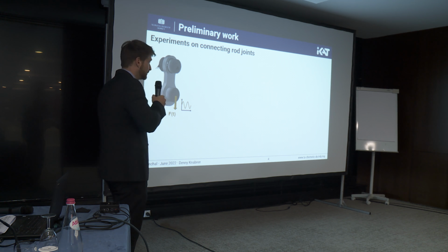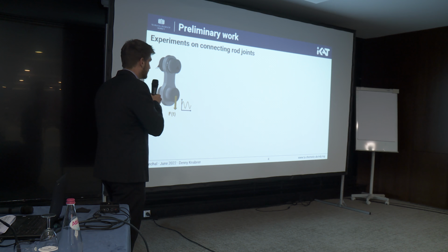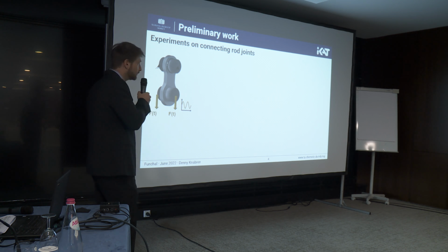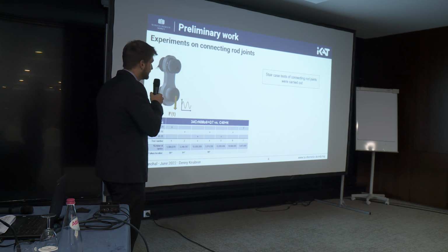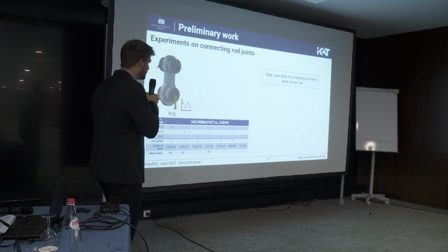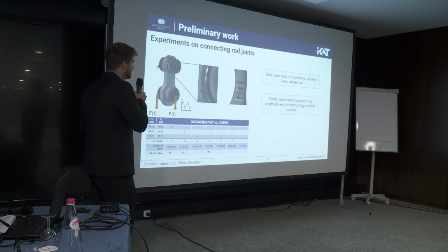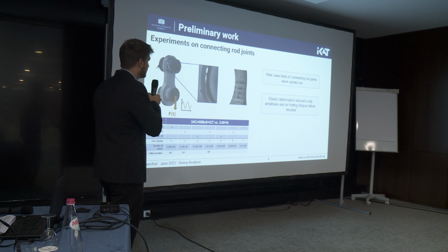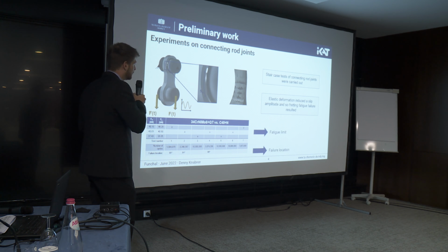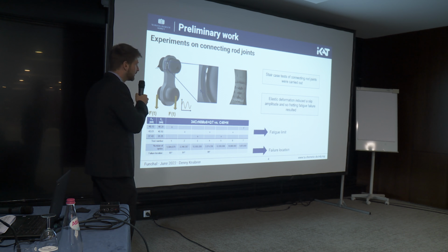So first we could validate them, but therefore we need an object for validation. Therefore we did some experimental tests on these connecting rod connections, which I mentioned before, and we did some staircase tests in the high cycle fatigue domain. You see we have runouts with 10 million cycles, and furthermore you can see these connecting rods clearly failed due to fretting fatigue. You see the fretting scars, and this is due to elastic deformations in the parts here, and these elastic deformations caused these micro slips, and so the failure occurred. From these experiments, we get information about the fatigue limit as well as about the failure location.